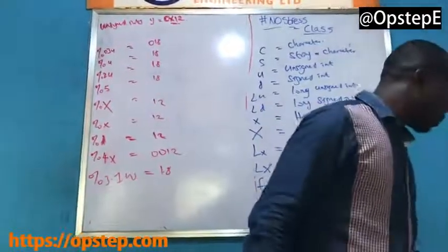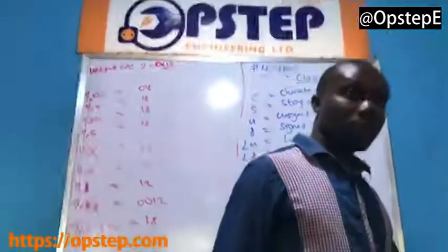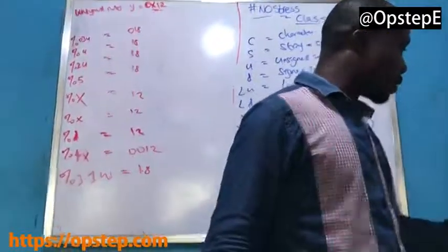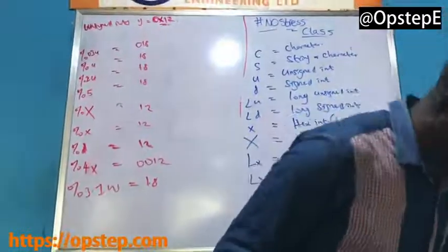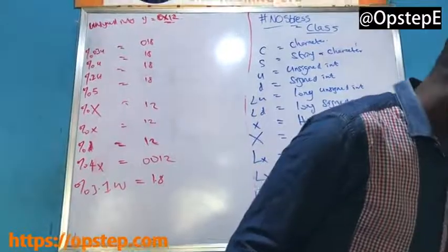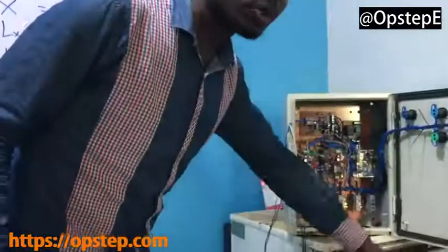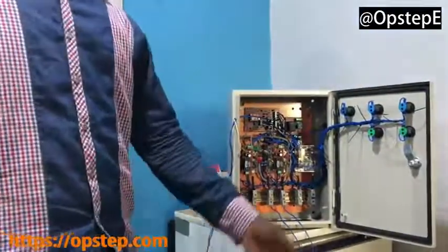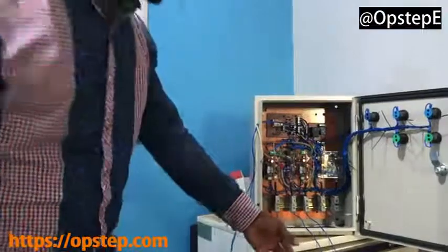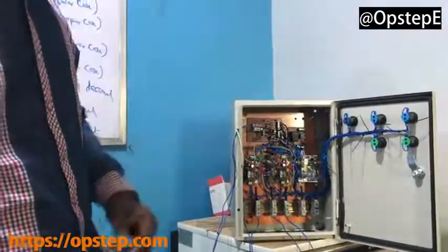This is supposed to be where the battery comes in. The battery, and then this is the indicator. This is where you feed NEPA in, live neutral. This is where you feed the generator, live neutral. This is where you tap out your load, live neutral too. And don't forget, in AC there are no polarities, so it can be live neutral or neutral live, it does not matter. Sure you understand.